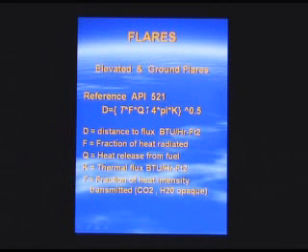API addresses shows you a flame length. It also shows you the option to go higher. That distance is from the flame. You can have the distance from the center point of the flame, or you can have an integrated distance of the flame divided into 10 points, so that each point in the flame is radiating back at a different level. The cumulative effect is also considered by API.